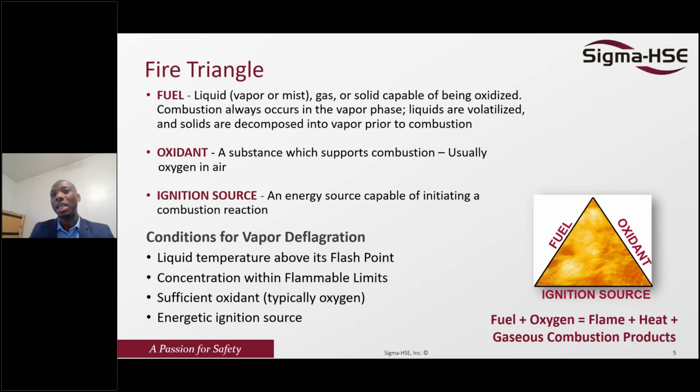So as a fire person, I think about the combustion operation first. First of all, do I have the fuel, which could be propane gas? Do I have sufficient oxygen, that is, oxygen in the air? Do I have an ignition source? In case I have my propane connected to my burner, that's the first thing. And do I have oxygen to sustain it? And normally you have to create something to create a spark to ignite it.